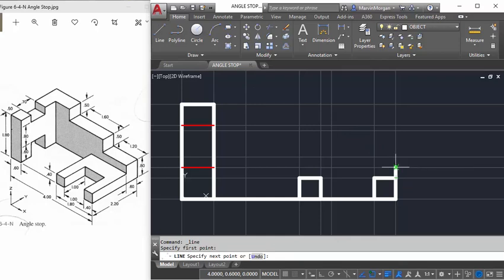Now notice this mark here. Remember, if you forget, just look at your image to see if there's any lines on that construction line. So I'm trying to go the 80 distance, which is located right here. But look, my red line is on this line. So I know this is not it because the red line represents my 0.60 over there. So I'm going to go to the next notch.